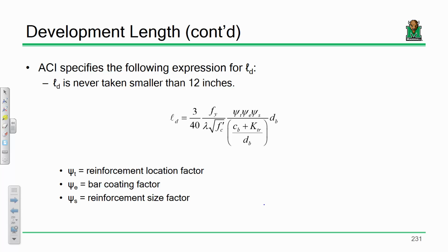No. You're talking about, are you saying the strength between the epoxy and the rebar? No. But really, from a capacity standpoint, we really don't care. The only reason that we're putting epoxy-coated bars is for corrosion. So we don't really worry. That's not really a big deal. As long as that concrete is completely encasing it, it's all going to act as one composite unit anyways. That's a good question, though. Any other questions? All right.